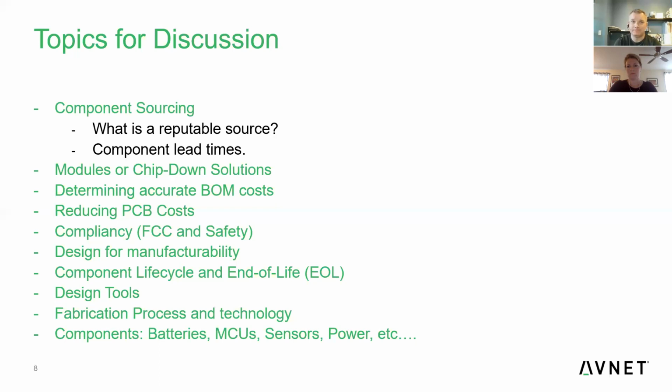Around safety, just jumping back, UL, CSA, most products that we see don't really have a strong requirement around safety, because most of them are using external adapters, and they're low voltage products internally. So typically you're using some type of external adapter that's going to drop down to 5 volts in most cases.